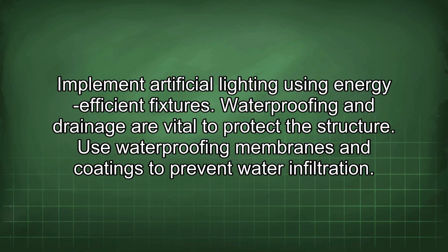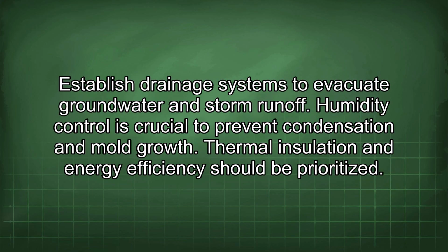Waterproofing and drainage are vital to protect the structure. Use waterproofing membranes and coatings to prevent water infiltration. Establish drainage systems to evacuate groundwater and storm runoff. Humidity control is crucial to prevent condensation and mold growth.